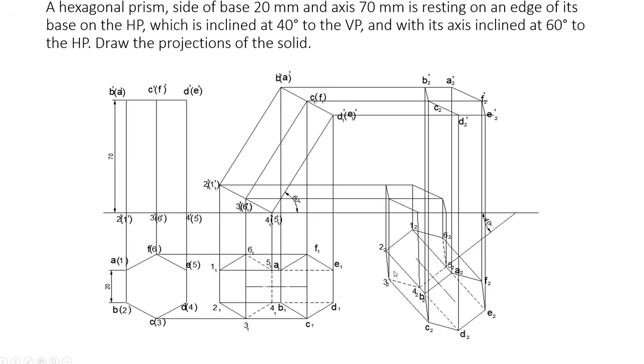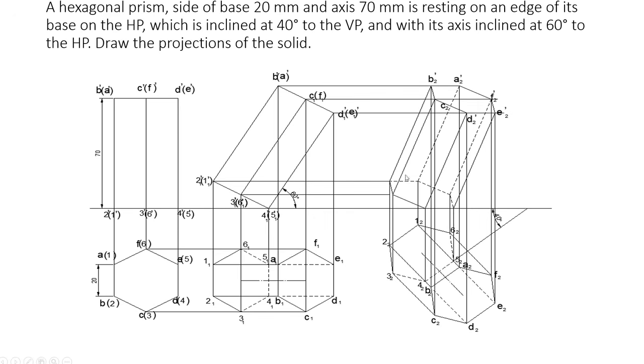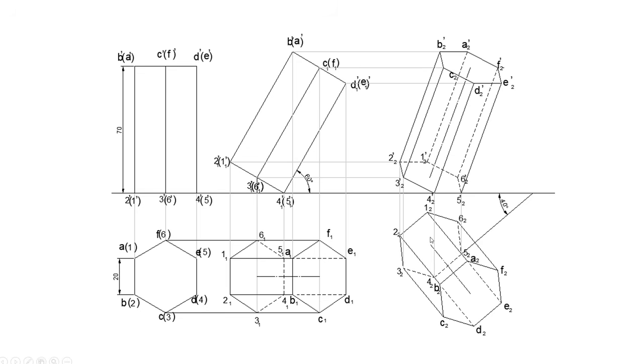Similarly here also you will project the other base points to the corresponding lines here. So you will get some points here, and connect those points and make a hexagon like this, a hexagonal prism like this. Now in this case also some lines will be invisible. How to find those lines? See here, in this diagram, how to find the invisible edges here.